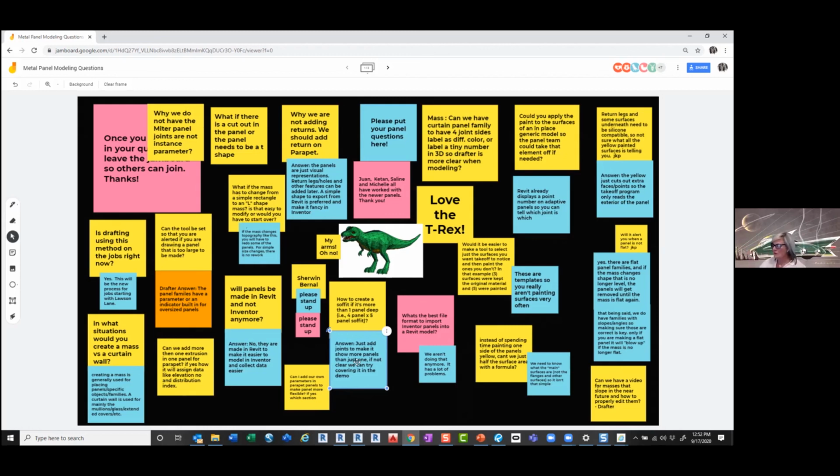If it just had a run of soffit panels and it's just 1 little band, I might use that tool. But on some of the other projects we have big underside areas where there are lots of panels. So maybe you have a mass and a face, and you make a curtain system and apply that flat panel, and that's where you would add in the grids. Just add more joints, which is what this sticky is saying. If it's a curtain system and you've put a flat panel in it and you want to add joints, that would just be adding those curtain grids.